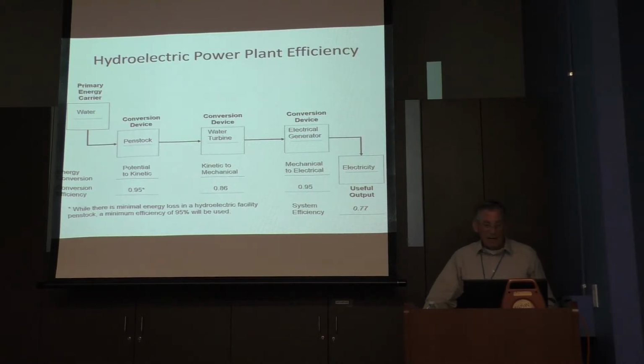I was never able to find anywhere on the internet any mention of efficiency of hydroelectric penstocks. I'm assuming they're probably pretty close to 98, 99% efficient, but I just chose 95 as the minimum here for this particular calculation.